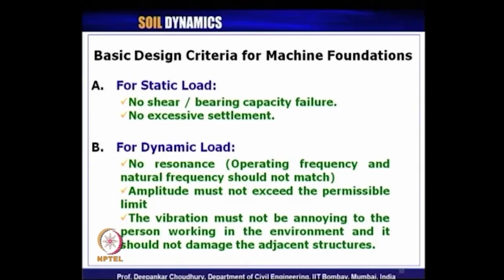And what is the third criteria? The third criteria is based on the vibration of the machine and foundation system together. It must not be annoying to the person working in the environment, and it should not damage the adjacent structures.